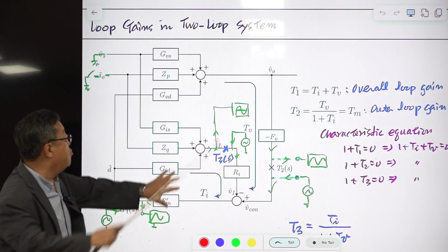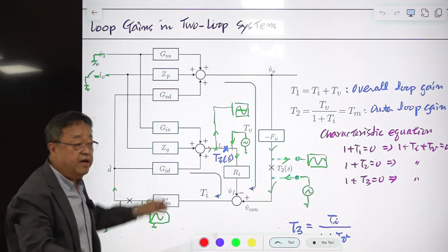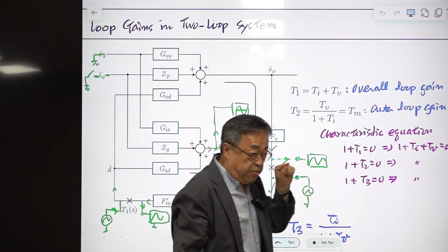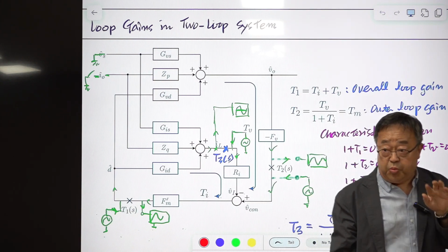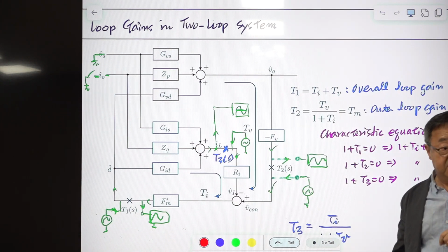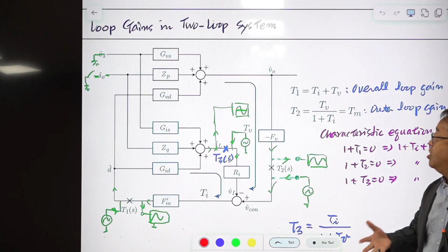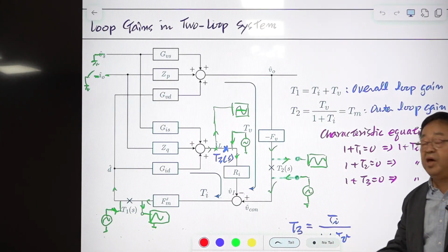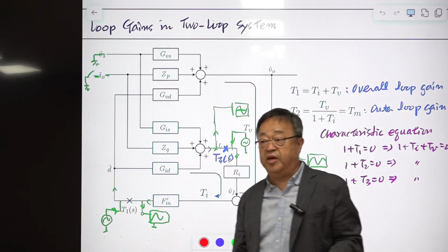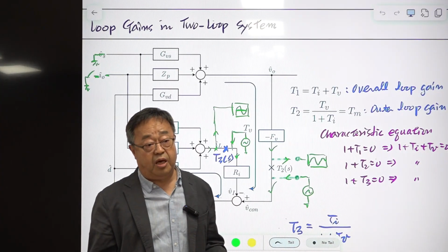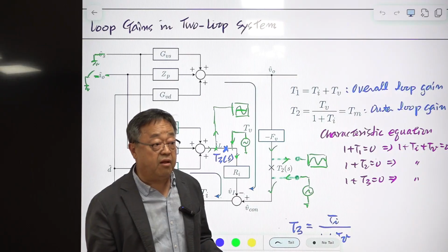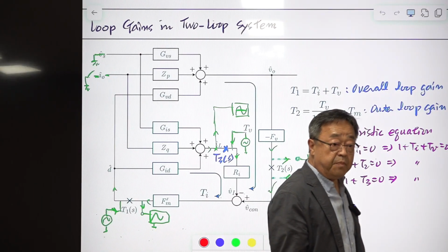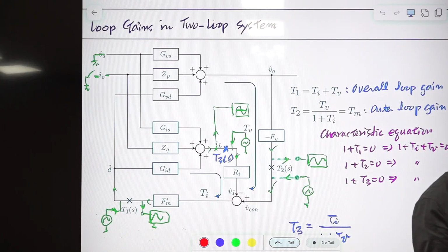There is only one loop gain here, and the magnitude and phase of the loop gain are uniquely defined because there is only one feedback. That loop gain carries the information about the absolute stability and the relative stability of the converter. So the implication of phase margin and gain margin for that case is very clear.